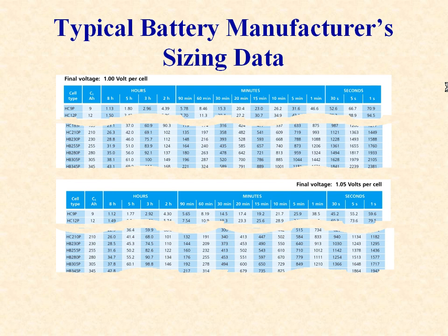The capacity data for nickel-cadmium batteries is normally provided in tables and applies to a series of cell sizes for a specific design. Typically 4 tables are provided, one each for the final voltage of 1.0, 1.05, 1.1, and 1.14 volts per cell. There are exceptions, such as the data for cells designed for high loads, such as engine starting duty. Parts of typical tables for final voltages of 1.0 and 1.05 volts per cell are shown here.